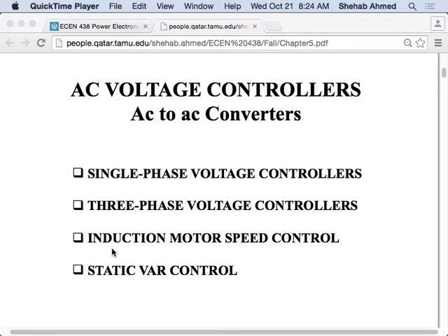So what does that mean? That means if I now apply a small voltage, not full voltage, across the motor's terminals at starting, then I will not get this huge inrush current, because I'm applying a small voltage across a short circuit initially. Then what's going to happen? This will rotate the motor a little bit. Then some back EMF will develop, so I increase the voltage, and so on and so forth. So I'm able to start my motor without this huge inrush current, and I get that benefit if I'm able to apply the voltage slowly across the motor's terminals.